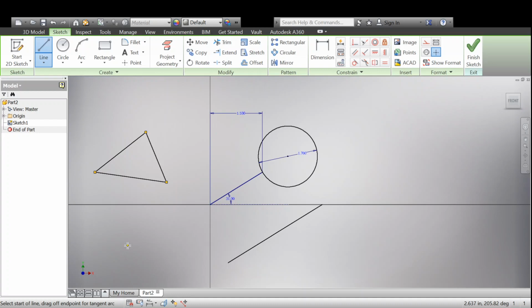Once you've made a triangle, please go back to the circle feature and take a look at the second circle feature, look at its command. The second circle feature takes any three lines and creates a circle that in this case is inscribed inside of those three lines. So I chose a triangle. By choosing this tangent circle feature, I can take a look at what it says. It says select second line. So it already thinks I have the first line, which I don't. So let me go back and hit escape for a second because that's not right.